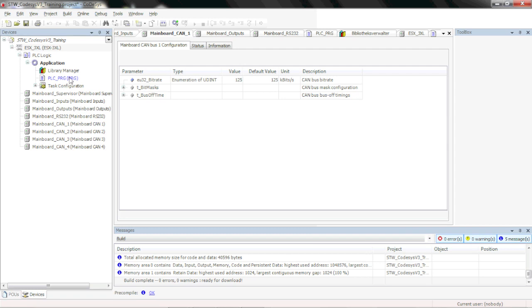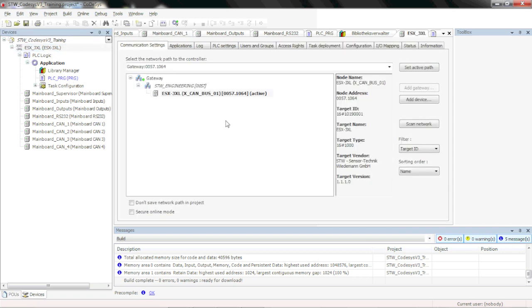Another problem that you could run into in that same thing is if your program is not even running on your controller, there will be nothing for the gateway to connect to. So if it's not connecting, you might want to check to make sure that your controller is actually on and running. And in this example that we've created here, our little project, we had that LED that was changing color to let you know that the program is still running.